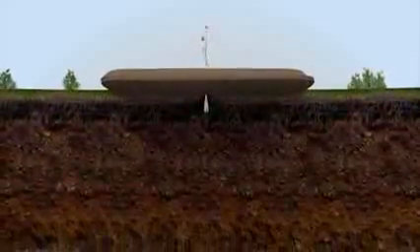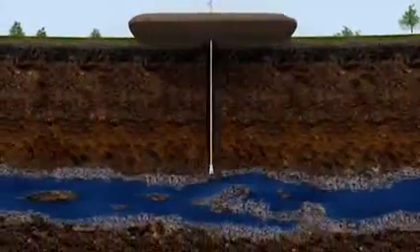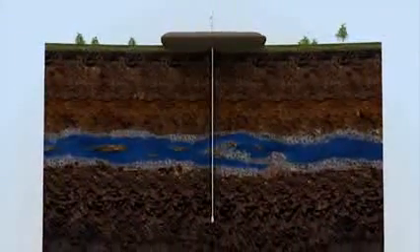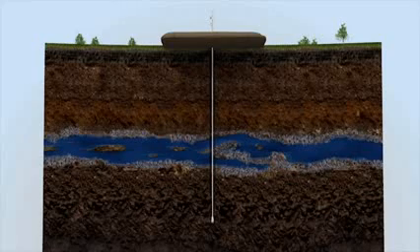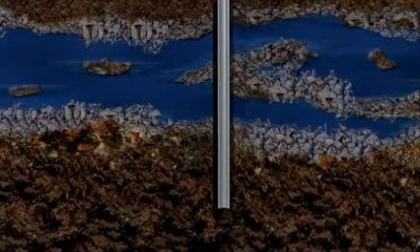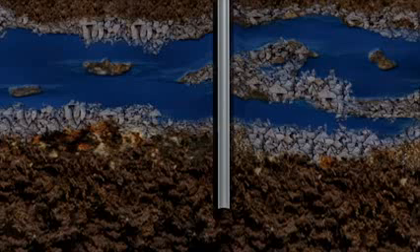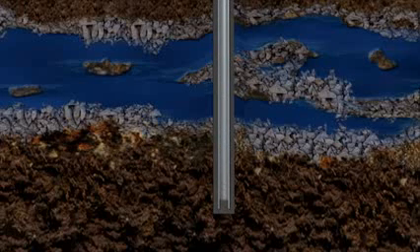The initial steps are the same as for any conventional well. A hole is drilled straight down using fresh water-based fluids, which cools the drill bit, carries the rock cuttings back to the surface, and stabilizes the wall of the well bore. Once the hole extends below the deepest freshwater aquifer, the drill pipe is removed and replaced with steel pipe, called surface casing. Next, cement is pumped down the casing. When it reaches the bottom, it is pumped down and then back up between the casing and the borehole wall, creating an impermeable additional protective barrier between the well bore and any freshwater sources.